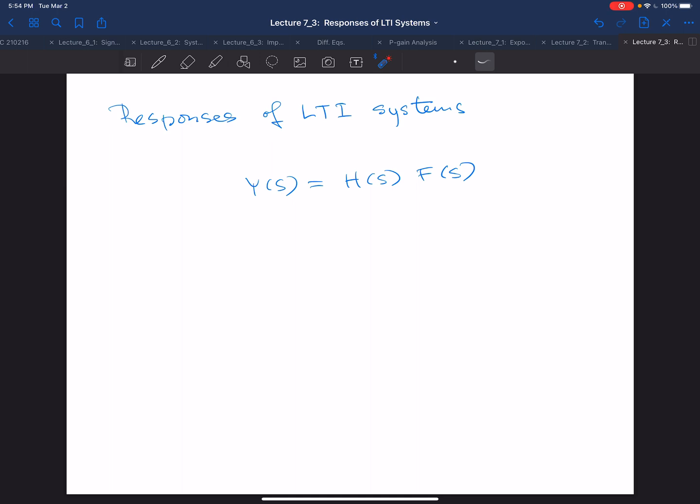So we'll certainly look at the form of the impulse response of a system with a given transfer function H(s). But now, a unit impulse is not the easiest signal to generate. In the continuous time setting, it's an infinitely high, infinitely narrow spike. So on a test bench, it's often a lot easier to generate something like a unit step input. So we'll look at the responses to unit steps as well. But we won't be considering too many different inputs. We'll mainly be focusing on the form of the transfer function and the way it affects the response of the system.